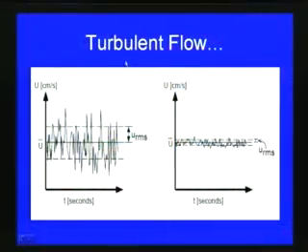You can see in this figure how we express this root mean square component. This is the velocity distribution, with time on the x axis and velocity on the y axis. You can see how the variations take place with respect to the mean component, and here we express in terms of u RMS, that means the root mean square of the velocity fluctuations. That is also expressed on another scale; u RMS is shown here. This root mean square of the velocity is generally used to express the turbulent fluctuations as far as turbulent flow is concerned.